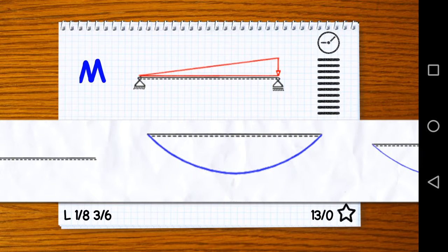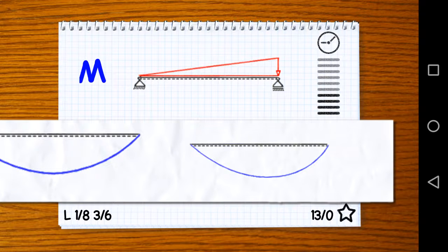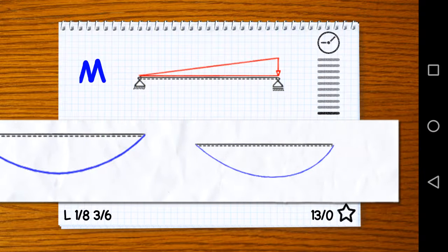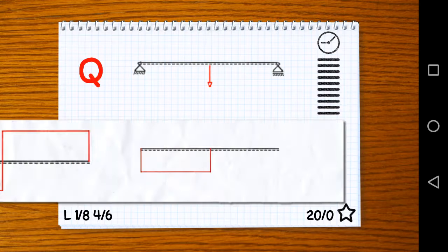So now what do we have here? We have a distributed load. It's not a constantly distributed load, but it's still a distributed load. On the left side we have a pin support, so we can't have any deflection there. On the right side we have a roller support, no deflection either. And in the middle we're going to have a deflection downwards. That's going to be a negative curvature, meaning a positive bending moment. Now, this could be this one or that one, but you can also see that since the distributed load is not constant, we cannot have the same change of the slope. It should be a little bit more here towards the right. That's why it's the right answer.